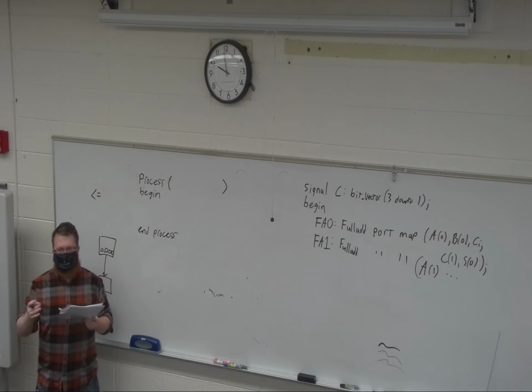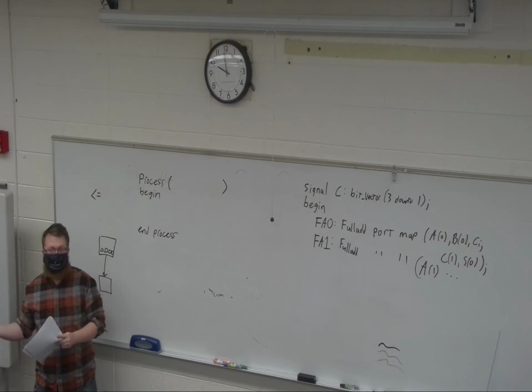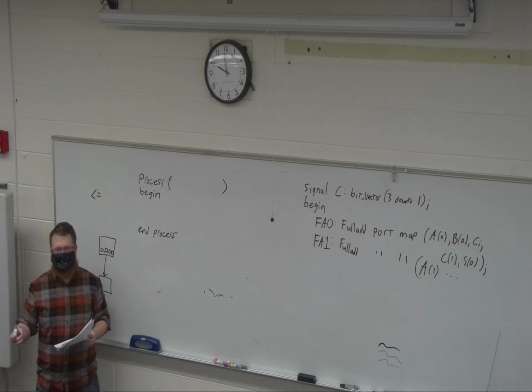If you're trying to use a process to represent combinational logic, so not clocked, it can be very difficult to get it to work. So be careful using processes on combinational logic.